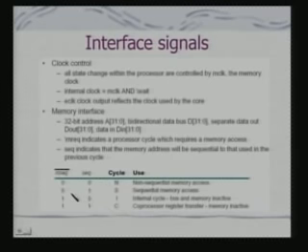Now, here we have given a set. What it tells you is that M request indicates a processor cycle which requires a memory access. It is not that all processor cycles require memory access. So external devices have to be told whether a memory access is required or not, and also whether it is sequential or non-sequential. That means whether you are accessing a memory location which is sequential to that used in the previous cycle or not. That enables appropriate design of the hardware.